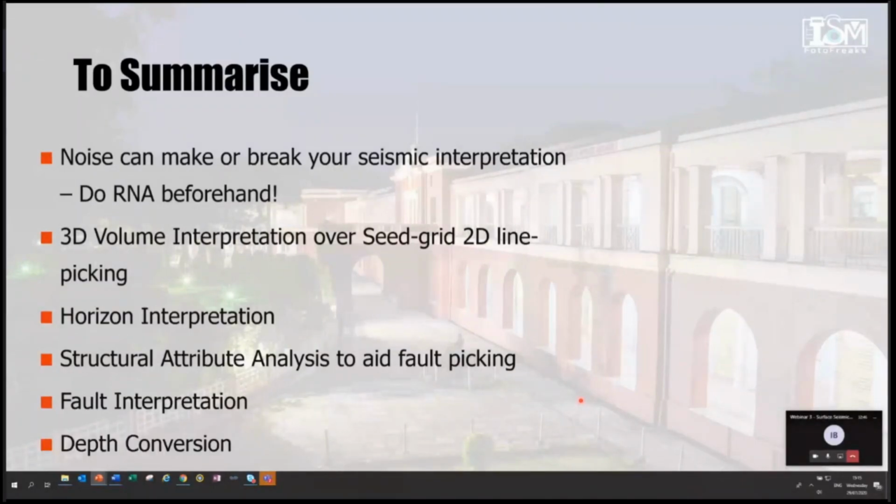Depth conversion is needed to obtain structural data positioned in depth from data recorded in time, as I said. But you do that with the help of layer cake velocity models, which basically represent the variability that you see in rocks, both laterally and vertically, and allow a combination of several sources for velocity information, including your migration velocities, your sonic velocities, your check shots.